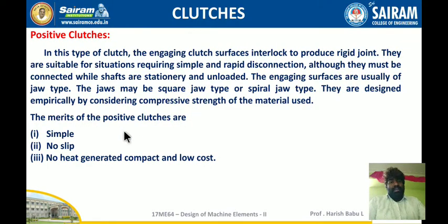So what merits are we going to get from the positive clutches? It is very simple, no slip will be there and no heat generated, and it is compact and low cost. Since it doesn't have any friction surfaces, the heat generated will be zero.